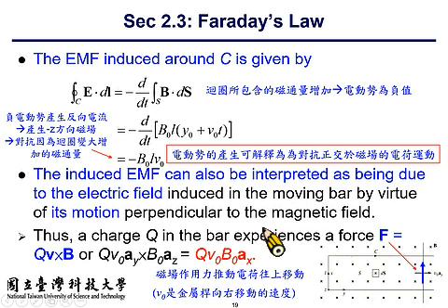So for this case, as from our previous derivation, we know that as the bar moves to the right, there is a current flowing counterclockwise to produce dots, to produce magnetic flux that cancels out the increased amount of background magnetic flux.